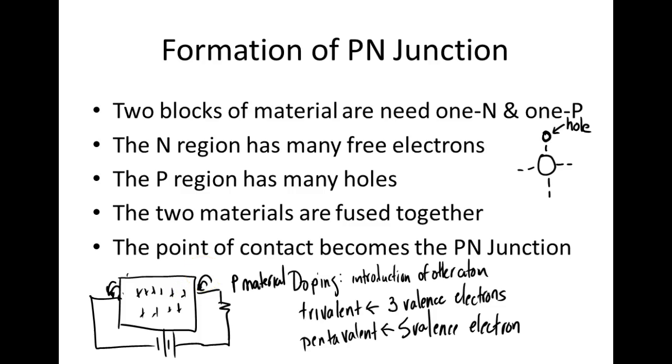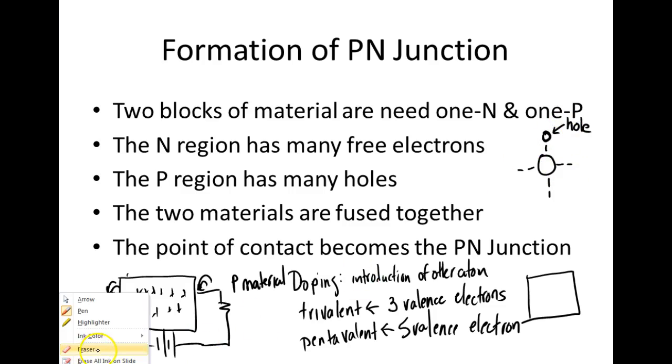Now, if I come over here and take another material and dope it with a pentavalent, then what we end up with in a crystal drawing like this is, on one side, instead of having 2 little electrons, I have 3. So now instead of having 8 out here, it has 9. What does it want to do? It doesn't like that 9th one spinning out there, so it'll release it. So these electrons are just floating around inside that lattice, just like the holes, waiting to be moved.